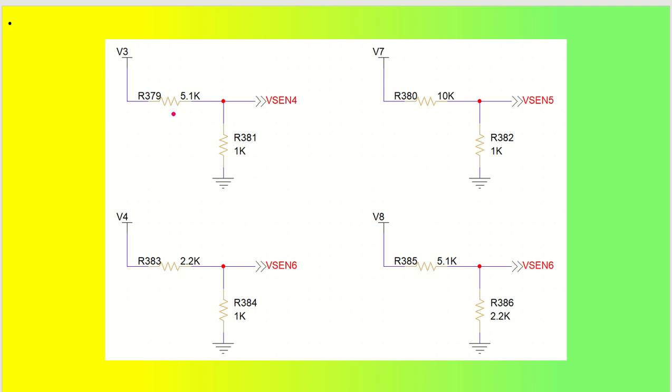Similar to that, other voltages can be possible, like V3. Let us say it is 9 volt, and let's say this one is 10 volt or something. As you can see, we have resistors R1, R2, R1, R2 everywhere, and our aim is to identify Vx, calculate it very quickly, and understand that the voltage being monitored is well within the range.